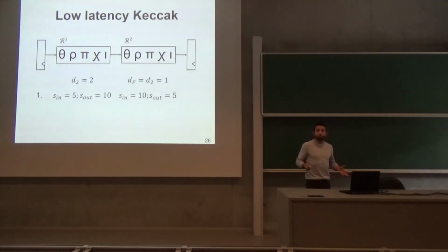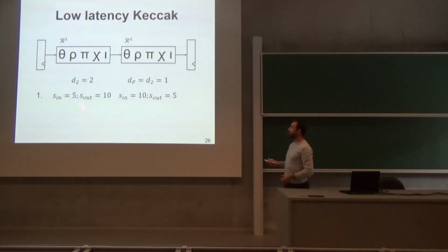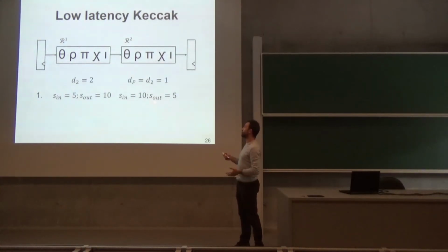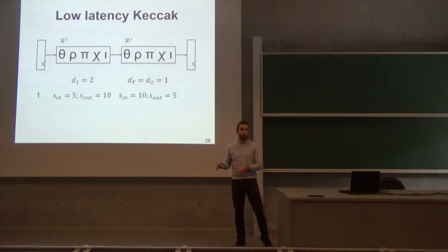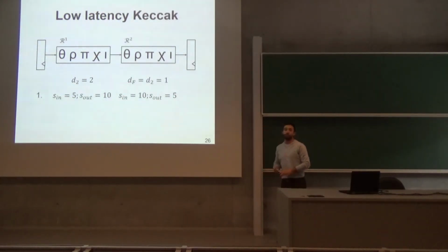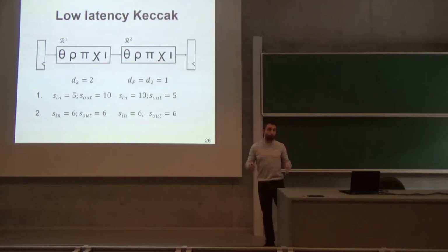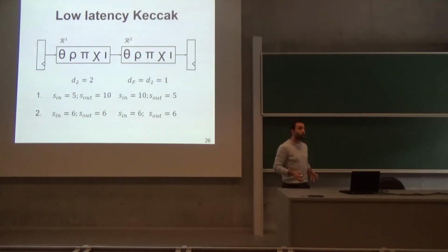We have a first option following the straightforward equations from TI. First sharing scheme, the second order, 5 input shares, 10 output shares. Second layer, 10 input shares, coming from the previous output, and we do a compression sharing to go back to 5 shares. So a 10 to 5 sharing scheme for first order, that's much more than normally needed, right? Second option, we try to find a more optimal way. We use 2 6 to 6 sharing schemes.